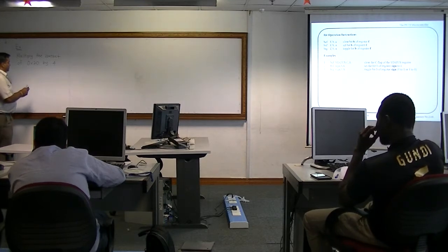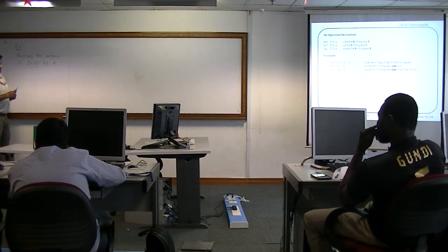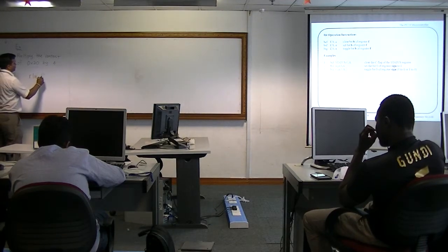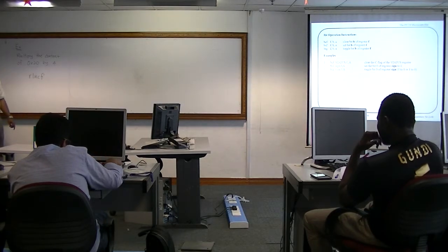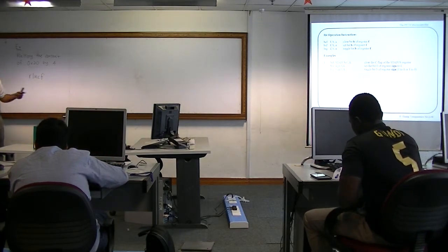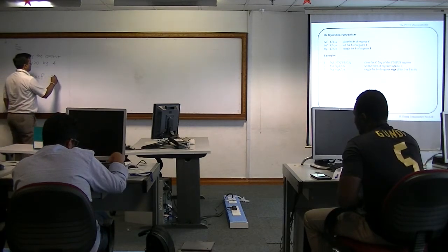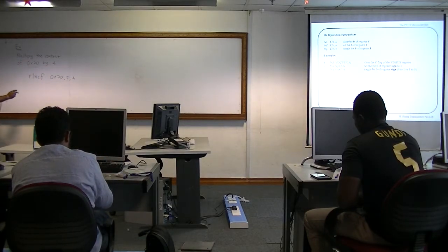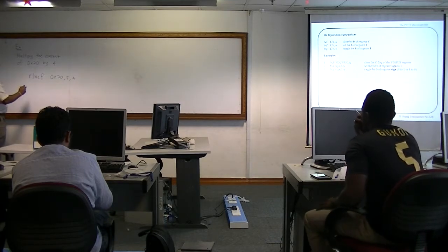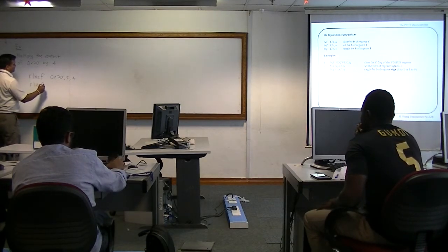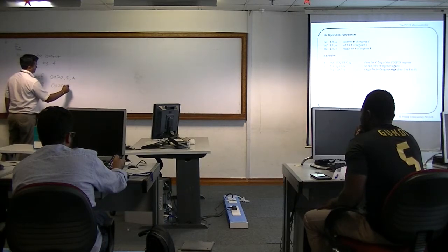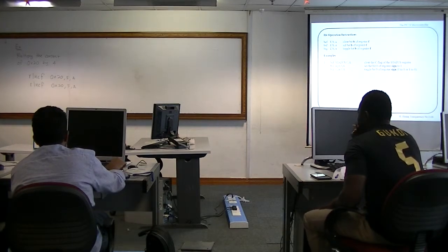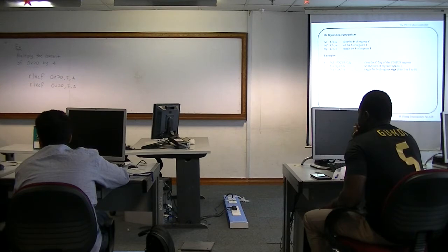So this one is a single byte value, right? So for a single byte value, you just use rotate left not through carry. You don't have to use carry. All the examples we did are not through carry, it's just within the register. So first time you do it, the answer must be stored at its own destination. When you do this one time it's multiplying by 2, but you say multiply by 4, so you rotate again. So it's multiplied by 4. Is it okay? Anyone understand? Any question?